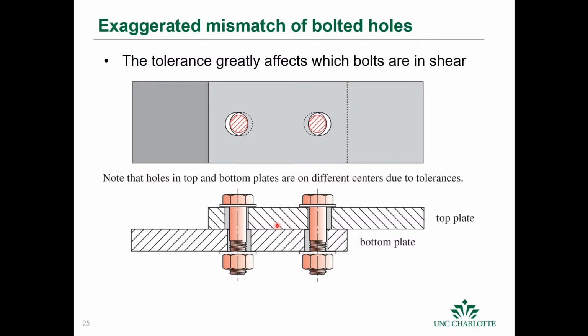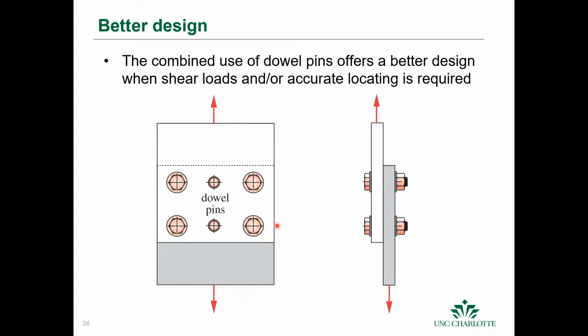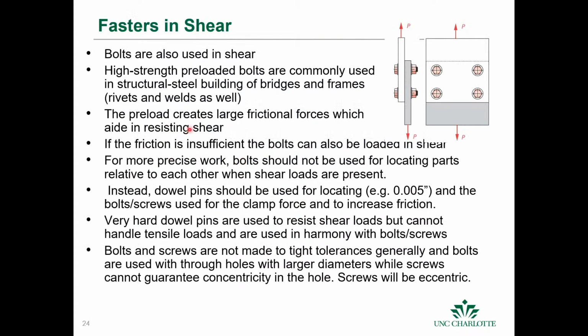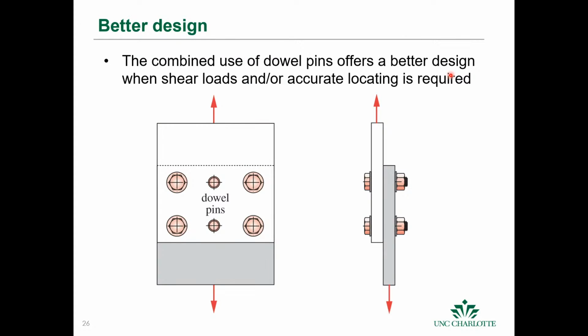And if you design the preloads right, then the material is going to take up those shear and axial loads. Okay, so this just shows an example where you have a better design. So this is your initial design for this plate here. And if you need any sort of accuracy, then you can have a design like this, which is a lot more accurate for locating. And it takes up a lot more of the shear.